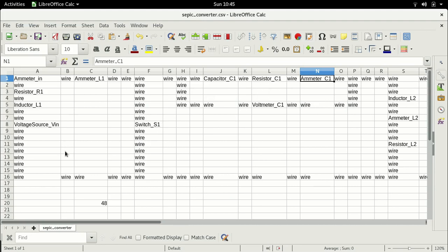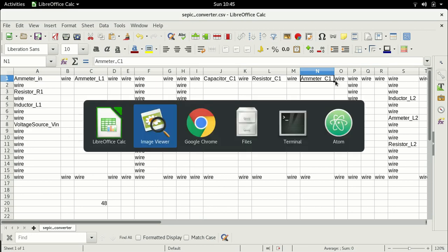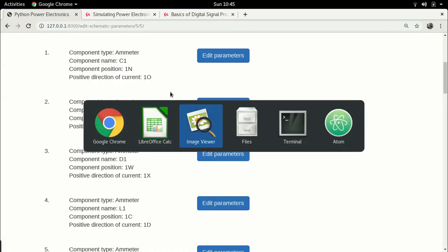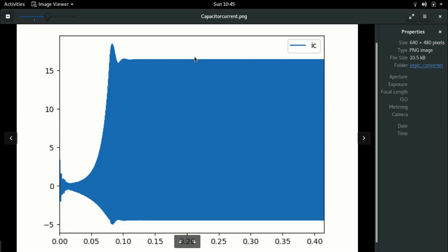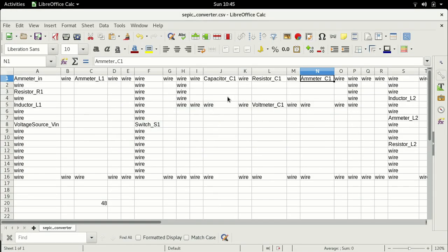Because when the switch is turned off, the input voltage and the inductor are charging the capacitor and the current is flowing towards the right, and that explains this positive peak, right? Whereas the negative peak is when the switch is turned on, the capacitor discharges through the switch. So this shows that the energy available during the off time from the input and the inductor is much larger than the energy which is available when the switch is turned on.